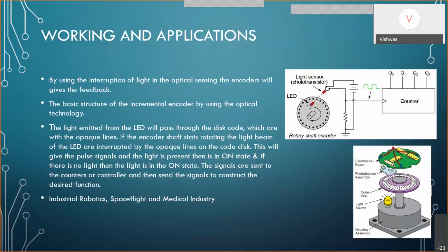If that is the case, we can easily count and deduce at what particular angle the whole thing is standing, just by reading the counter. Let's say you start from 0 and have 360 for 360-degree resolution. You will be able to tell that this is at exactly 90 degrees, this is at exactly 95 degrees, like that.